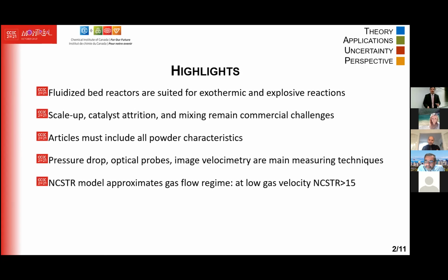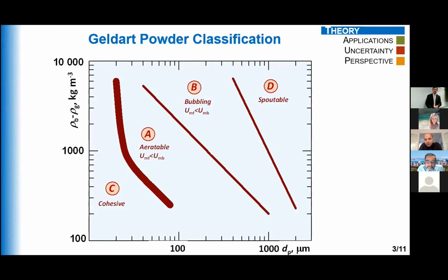I advocate fluidized beds as a means to measure kinetics. The reason I think that's interesting is that if you have complicated kinetics, with deactivation, solids buildup, carbon buildup, or changes in oxidation state, a fixed bed will have profiles, whereas in a fluid bed everything is backmixed. The only thing that's not as well known is the gas phase, and so what is the contribution of the gas bed?